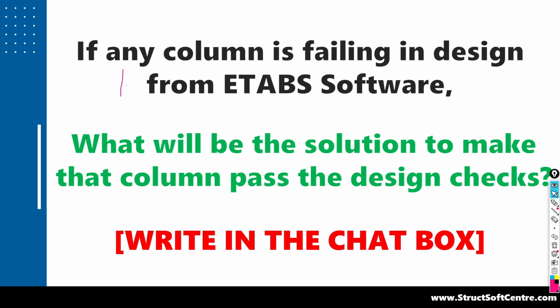Surya Teja Reddy is suggesting to change the orientation of the column. If it is vertically positioned, you can change the orientation to horizontal. Very good option. We can increase the grade. We can check the design parameters. We can change the design overrides. We can revise the design parameters. All these are the different options to get the solution or to pass the design of the column.